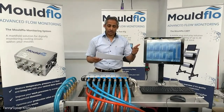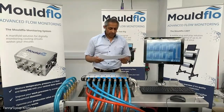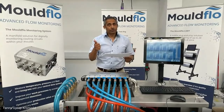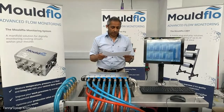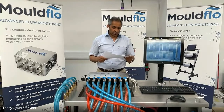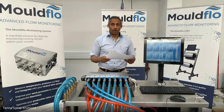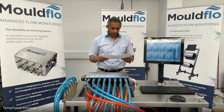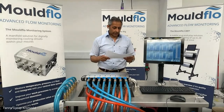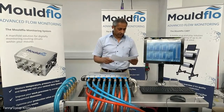First, we will do the flow test. Second, we will do the pressure test of the cooling channels, both with 2 mediums. One is with air and the other is with water. And then we will do the extended flow test at the last. Then we will wrap up, and we will clean the hoses for water and clean up after the testing, and then we will purge the water from the Test-Rig.